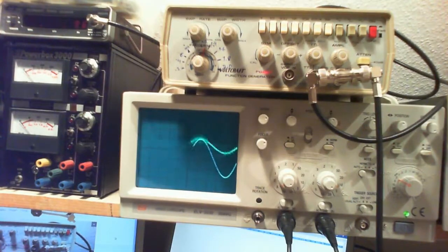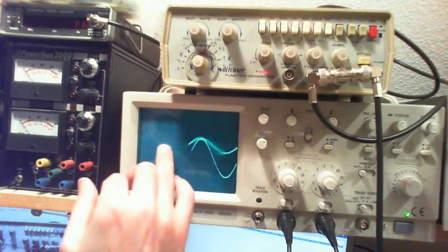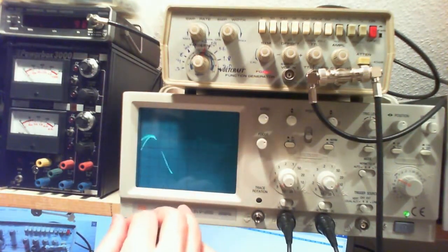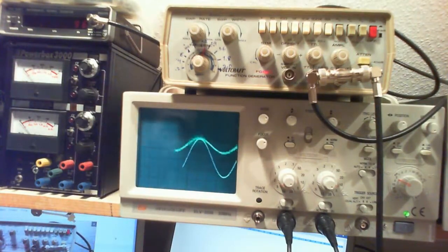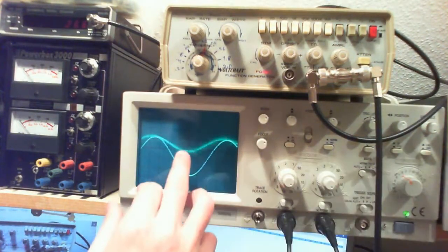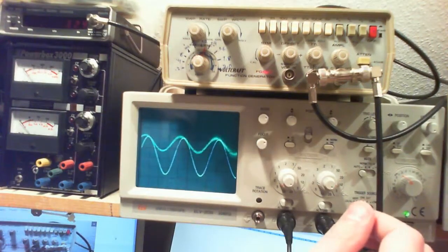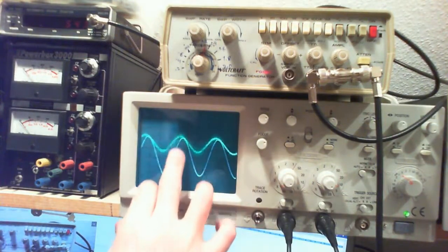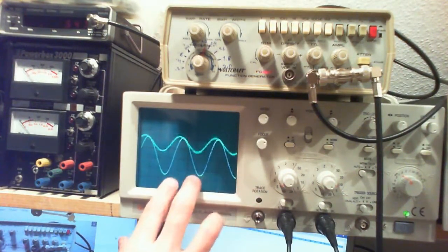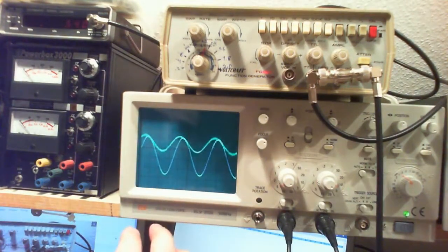About 100 hertz. Right now there is not much phase shift, and you see that the top wave is my output, and my output is still red. There is no phase shift still, but if I increase the frequency a little bit, you see that the output is leading. If this is 360, this is 180, and that would be about 20-30 degrees or so.